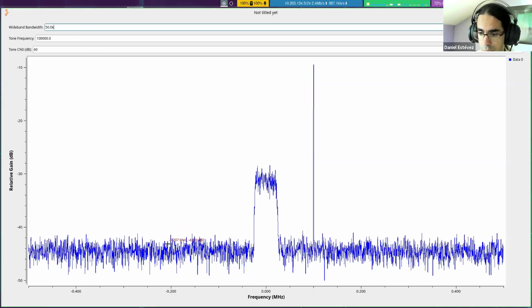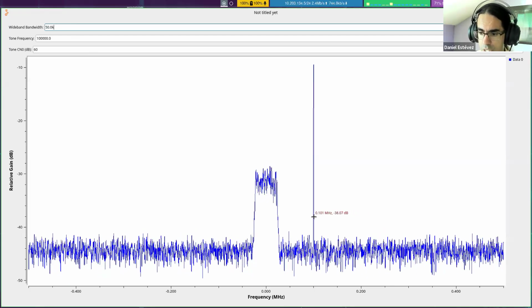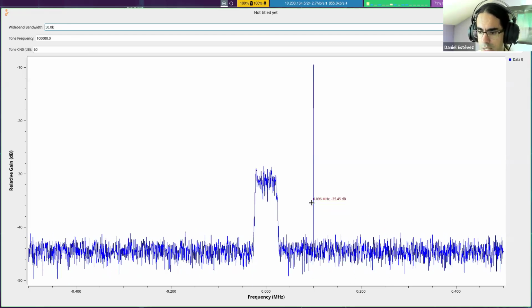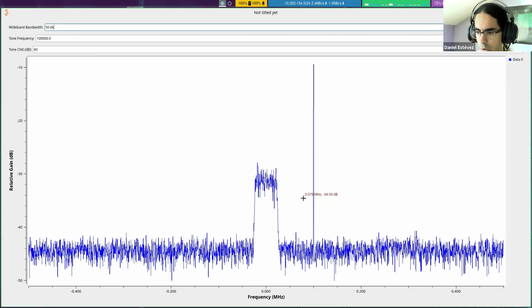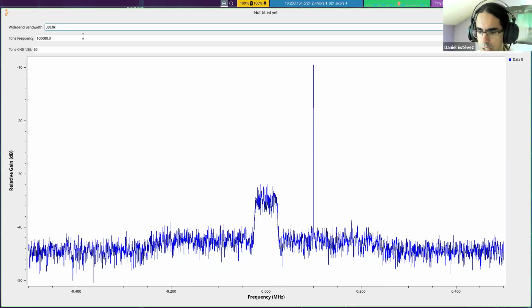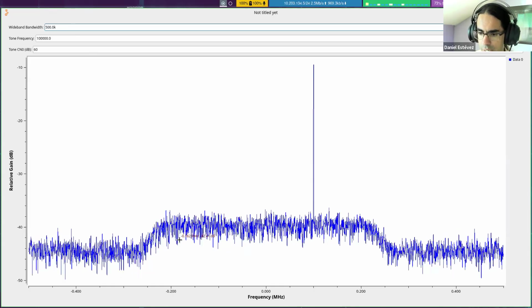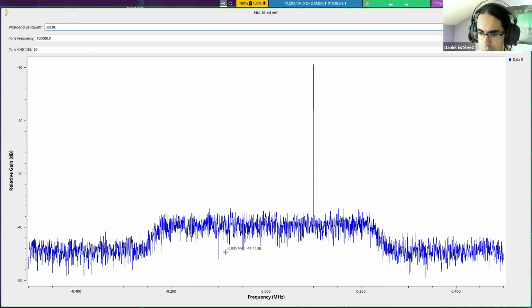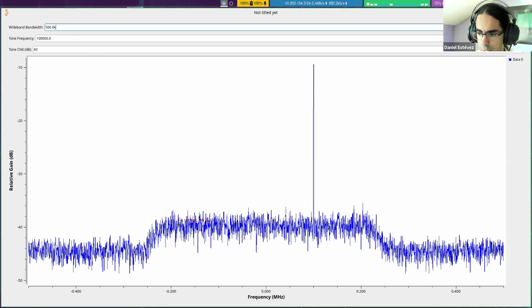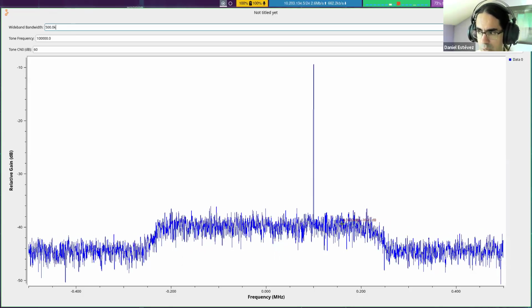This is just because of constant power, but the thing which the FFT is plotting is not power, it's power spectral density, which is how much power over frequency we have. So that's also something to keep in mind. Just because you see that some signal is really tiny here, it doesn't mean that it's necessarily weak. If it's wideband, then you need to integrate all the power across the bandwidth of the signal.